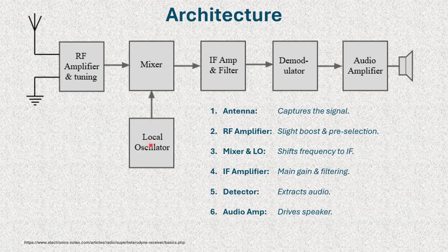We just adjust. This is where our tuner dial is in the local oscillator. We change that frequency that is being injected into the mixer, so it is going to give us the difference between it and whatever is out there that we're going to hit. And it's going to convert that to, let's say, 455 kilohertz for AM.